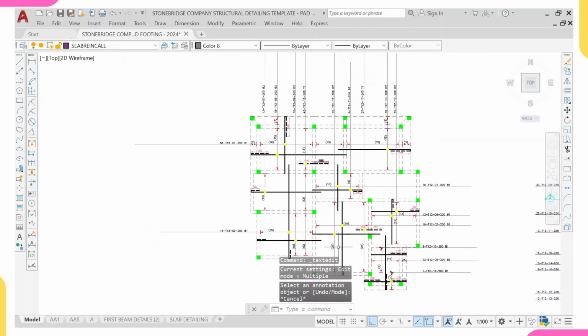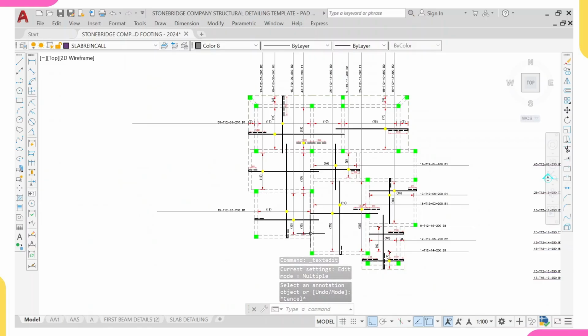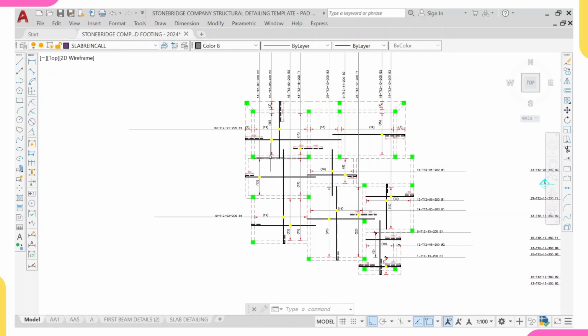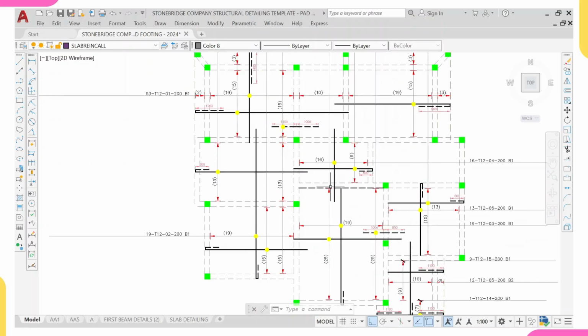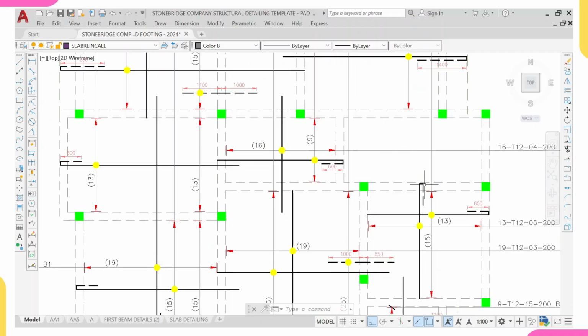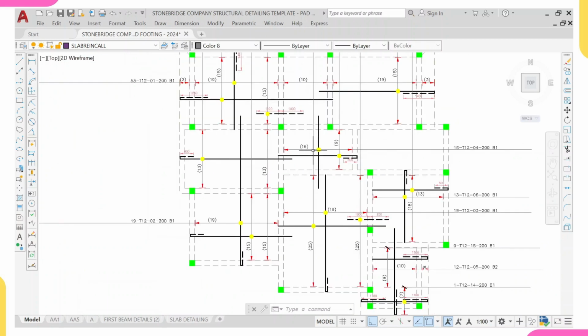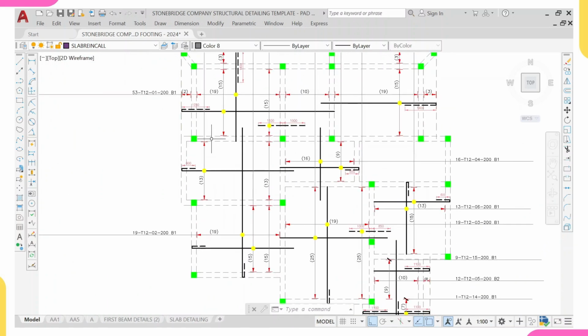So we are through with all the top reinforcements for this and for this. So let's come over to the horizontal one. We have top reinforcements here. This is staircase. Look at it, this top reinforcement has been provided for here again. I will only have top reinforcements here because this is a continuous beam. It will not extend to this. This is a staircase. In fact, it's only this beam and this beam that will be having top reinforcement.